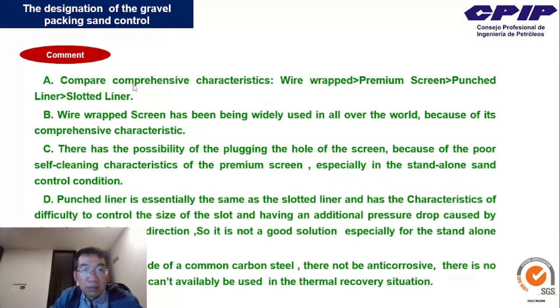Compared on comprehensive characteristics, wire wrapped is better than the premium screen, is better than the punched liner, and better than the slotted liner.